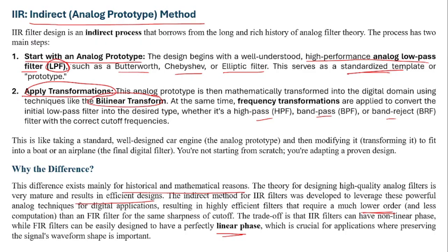If you want to manipulate the phase response, your amplitude response gets distorted. So over there, we come to a trade-off: I want this kind of phase response, and for maintaining it, if there are some deviations in the amplitude response, I will accept that deviation. And vice versa. So what is happening? You yourself are accepting that you are incorporating some discrepancies within the filter signal.